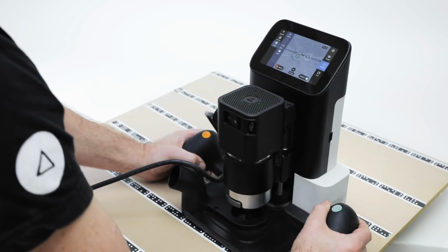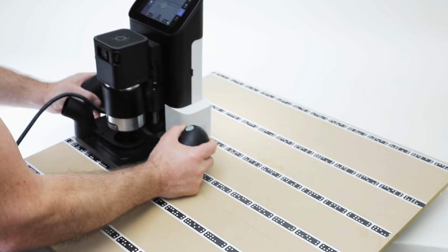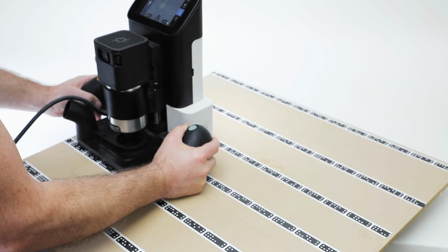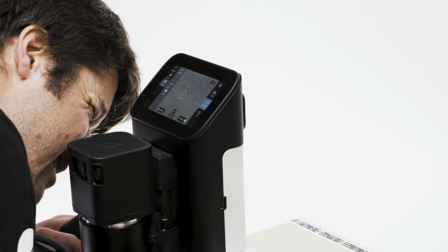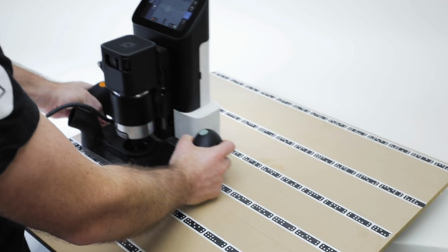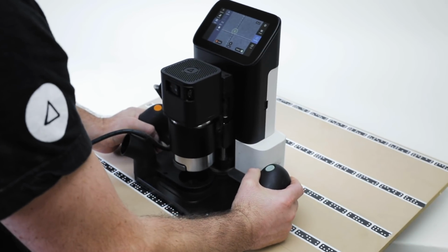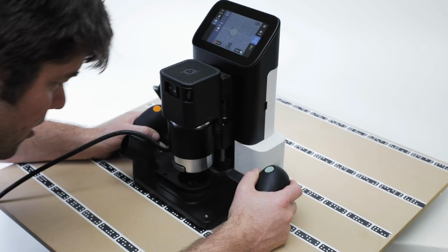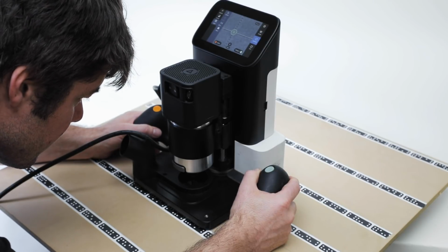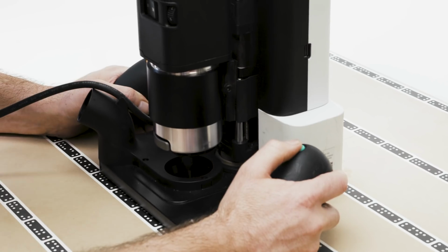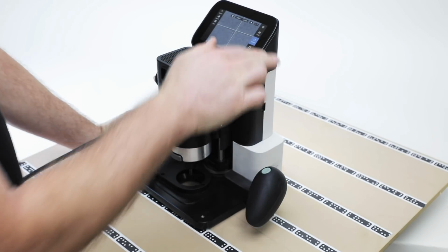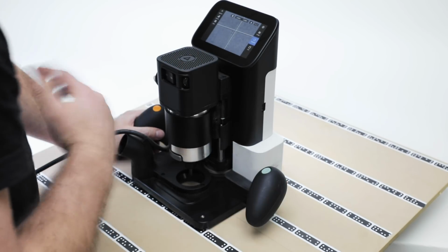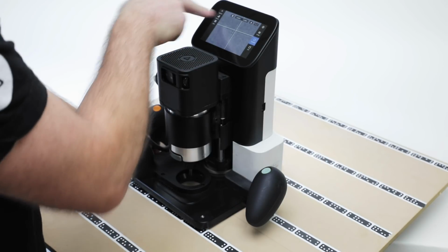So now as I drag, I can quickly see on the screen that I'm vaguely correct, but I'm going to confirm I'm where I want to be by looking down at that cutter hovering above my pencil mark. Once I'm happy with that, I move back to the center, and I can see it's automatically switched to the center mode for my y-axis as well. Once I'm happy with that, visually looking at the point again, not the screen, hit accept, and we've got a perfectly aligned grid here. So for projects in the middle of a large area, that's really powerful.